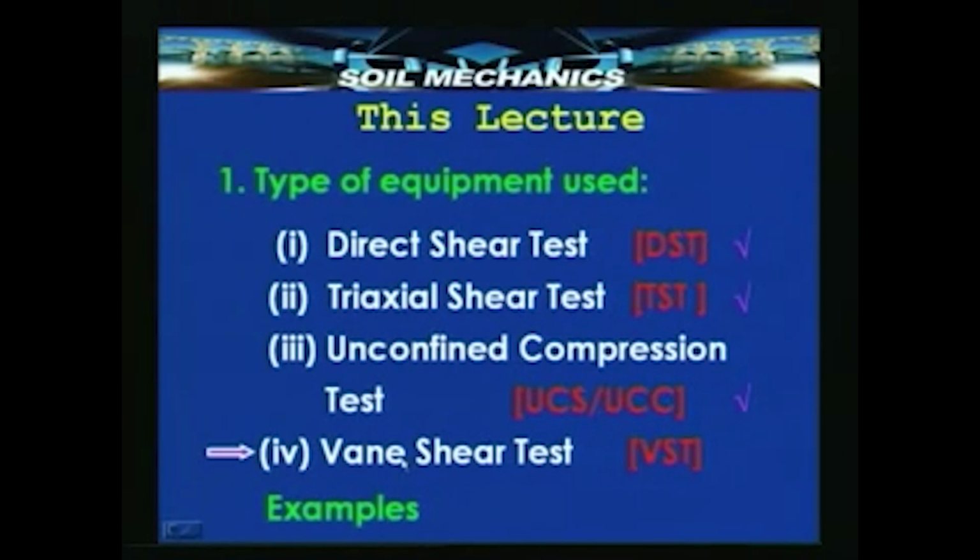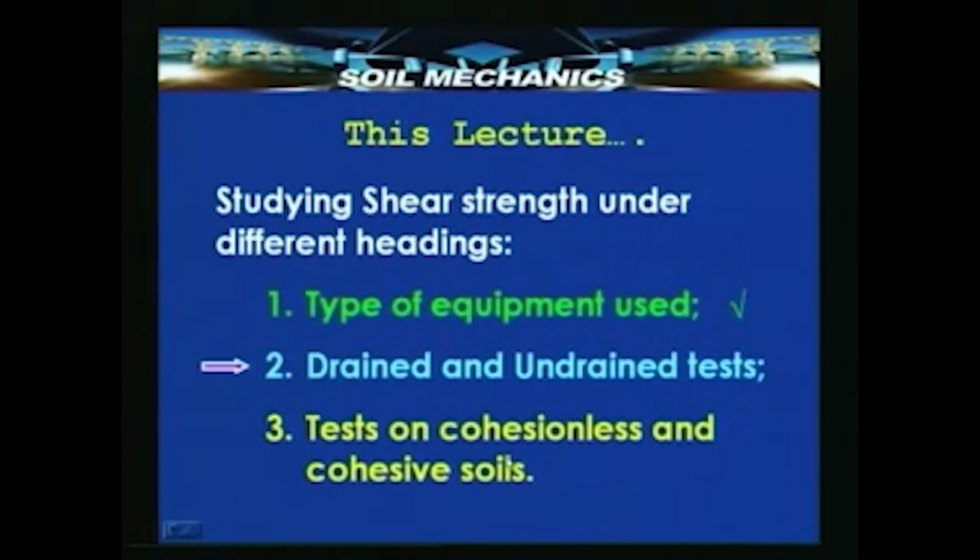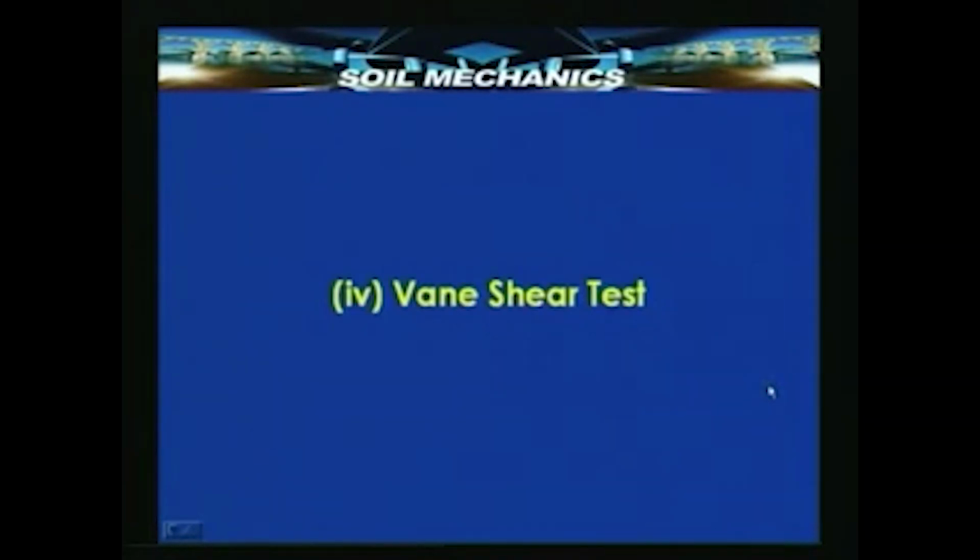In this lecture we will also be seeing the second aspect of my classification of the entire lectures on shear strength, that is, classifying the shear strength studies into those corresponding to drained state and those corresponding to undrained state. Let us begin with the Vane shear test.